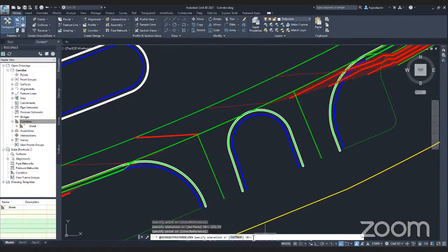Right, so this one will be 276.59. Before that, let me copy and then just click on enter again. Okay, so that has the elevation. Now this one is still 0, so just click again on that very end line and paste again the same elevation, and I click on enter, and I now have the same elevation.